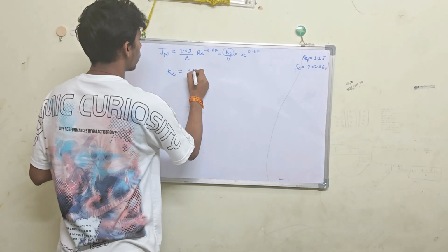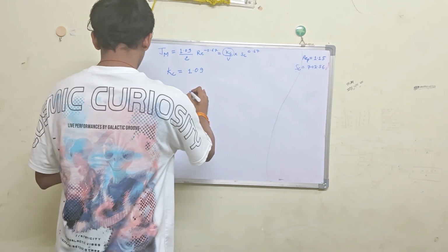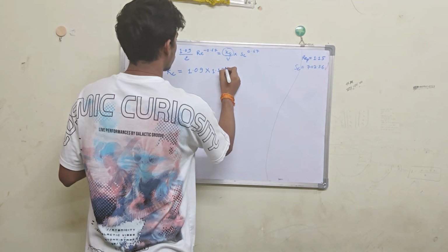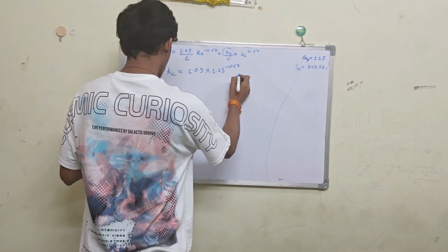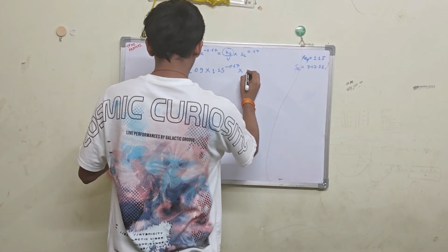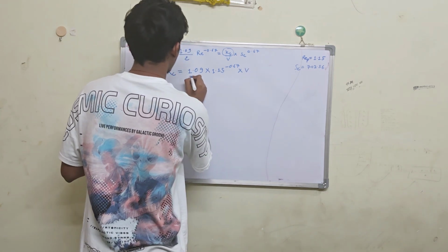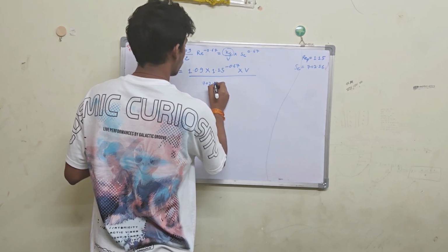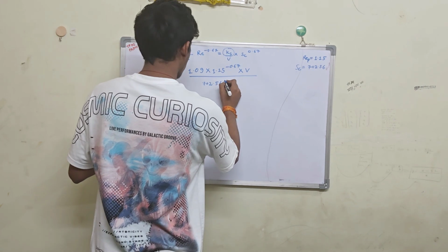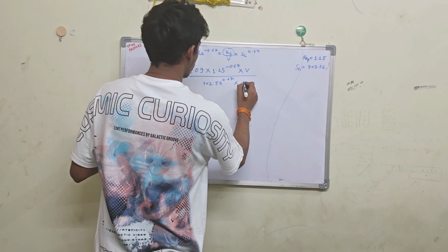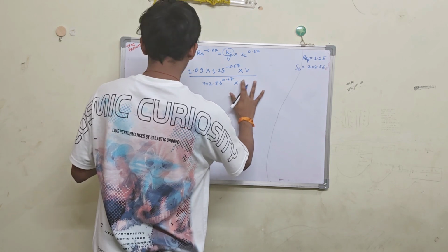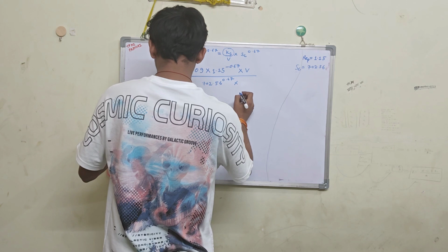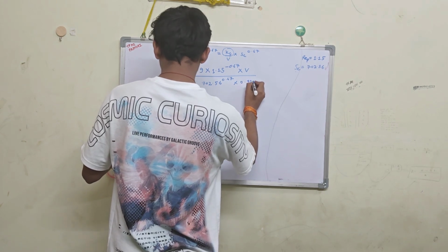Kc is equal to 1.09 into Reynolds number value 1.15 to the power minus 0.67. This velocity which we have calculated divided by the Schmidt number 702.56 to the power 0.67. Epsilon was given as 0.436.